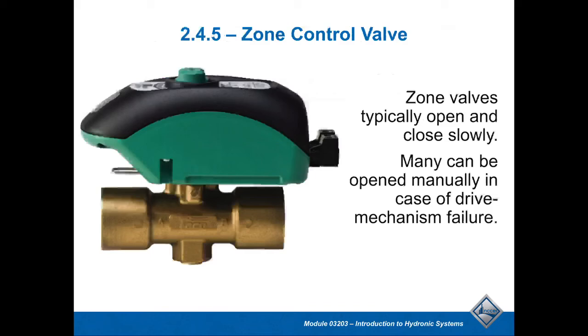All right, so let's take a look at zone valves. This is showing one style of zone valve, and one of the things with zone valves is we don't want them to slam open or slam shut. When we open up a system, we typically want them to drive over a certain amount of time. That could be 15 seconds, it could be 30 seconds in some situations, where they would open and close over those time periods. It's primarily to prevent a lot of water hammering effect on those. So that's really one of the reasons for that.